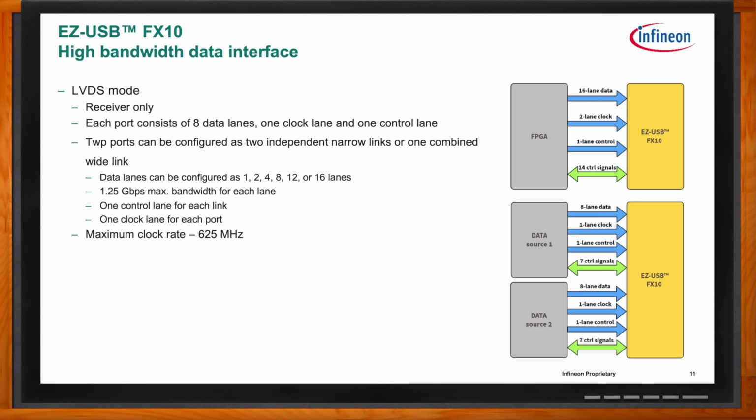So this interface will make the selection of an FPGA much easier. But with only unidirectional data, we still need to communicate to the FPGA. So you can use the control signal provided with the LVCMOS connection. You can then let the FPGA know if the link is ready or if the transfer is entering flow control. You can also use an I2C or SPI interface to communicate to the FPGA.